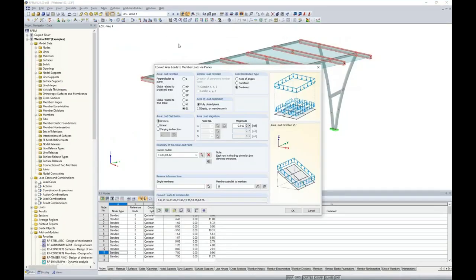So assuming that we have taken this information, we have determined what our magnitude should be for our structure today, we want to apply this in the lateral X direction. And again, applying this to my roof structure, we want to set the magnitude here to negative 0.01 kips per square foot. The program remembers all my settings for my roof.